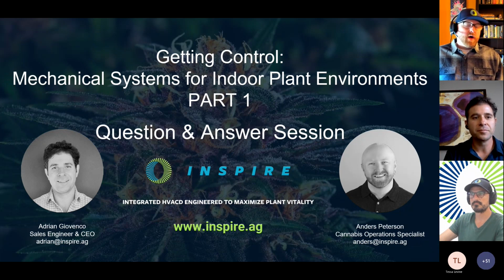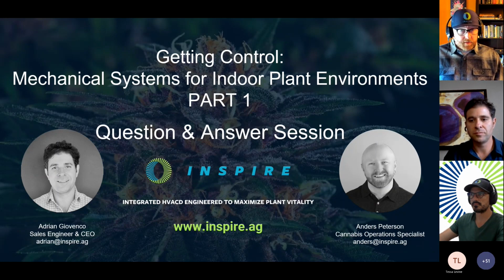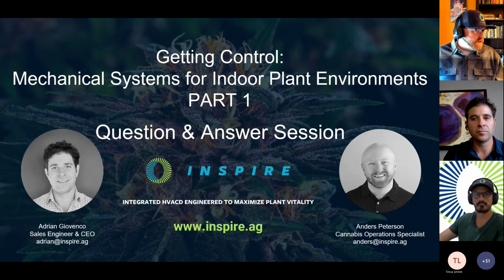Oh, and there are also driver losses to be considered, like in LED fixtures and HPS fixtures, because they're not 100% efficient, right? There are a number of ways you can get that. You can get it from the manufacturer, or you can try to reach it yourself with micromoles per joule efficiencies and PPF ratings from cut sheets, and start calculating these driver losses. I think a 1,000-watt HPS fixture is something like 1,050 watts actually at the end of the day. I forget exactly.